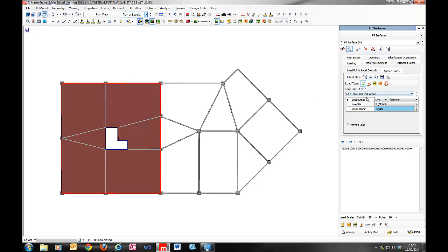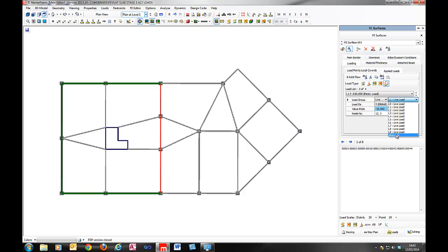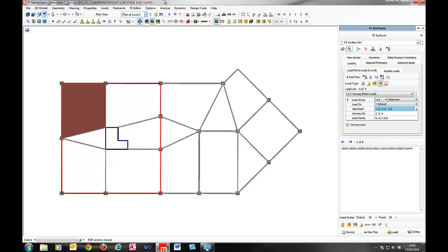So I don't want all my load to be always just L1. I want it to have the ability to split itself up into different load groups. And I would do the same thing for any other load essentially on this slab. Now the one other area where you need to make alternate is the density.